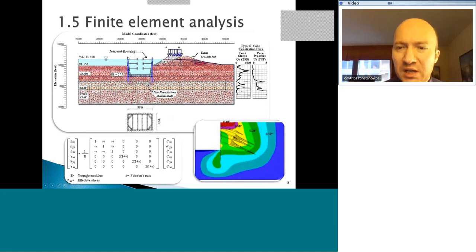We've also seen that with finite element analysis, the idea is that we divide the soil into smaller elements. We still have to include all the construction staging. That's the importance of soil structure interaction, that you have to build up on your previous states. We divide the soil, we create structural elements, we create boundary conditions, and we're capturing state by state what's happening.